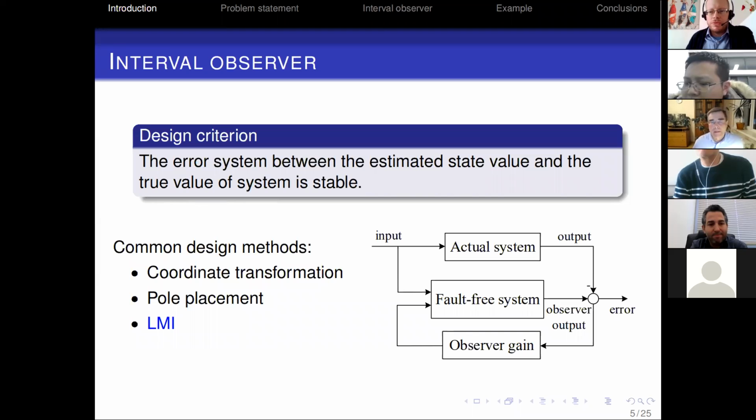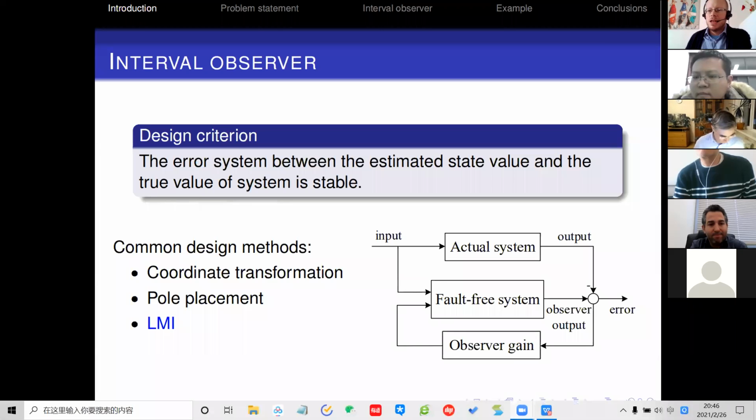Imposing, for example, from physical knowledge, restrictions on the domains of the resulting eigenvalues as further constraints on this LMI that you already have. Because if you know from physical considerations, for example, that the variations of some faults must be very slow in comparison to the system states, it does not really make sense to modify, let's say, the ratio between the absolute values of the eigenvalues in a very dramatic way.